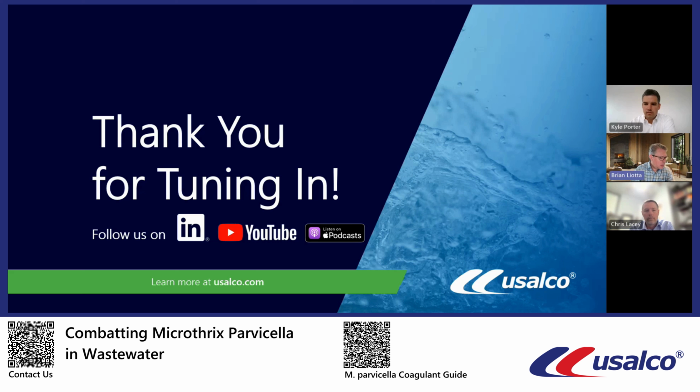Thanks, Chris. Next question. It's a typo, but I see what they're saying. Will ferric chloride work as well for treating Microthrix? No, ferric chlorides won't work for Microthrix control. Even basic alum won't either. It has to be one of these particular products that are a low to medium basicity PAC to prevent that fat lipid uptake. Anything to add to that, Chris? I'd say the same thing. Okay, fair enough.